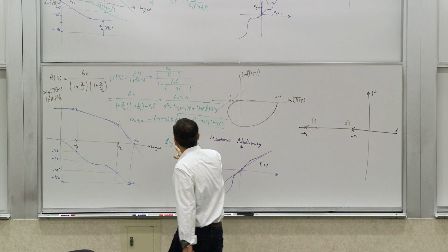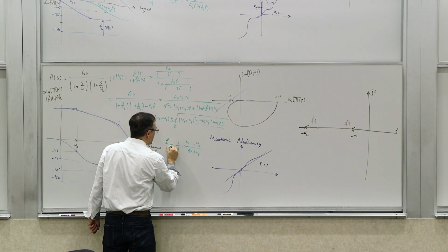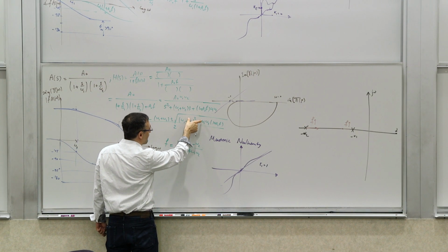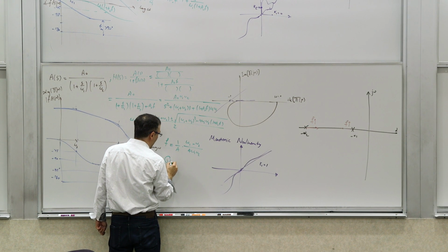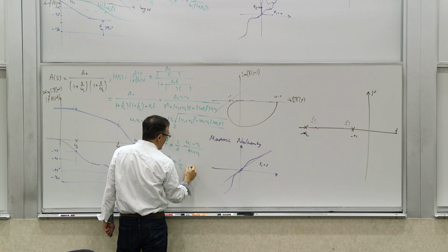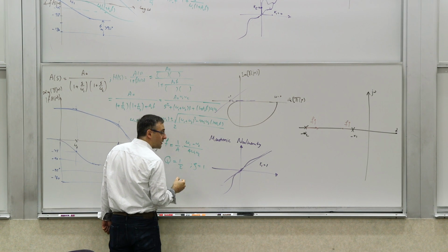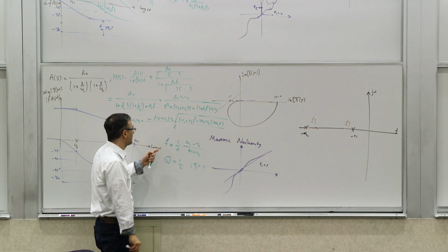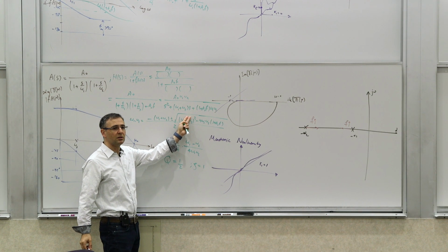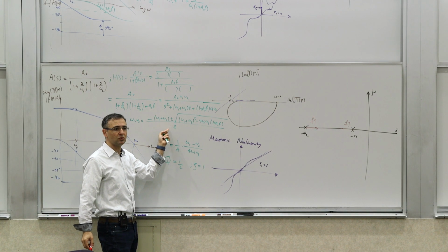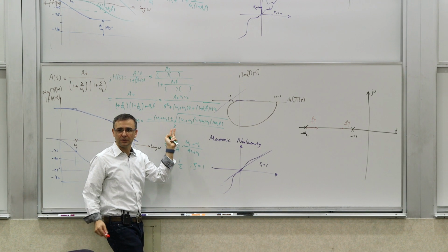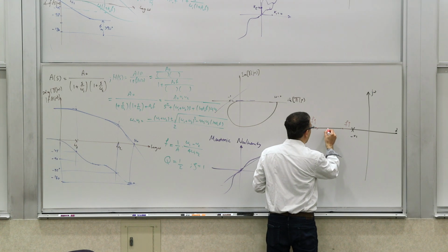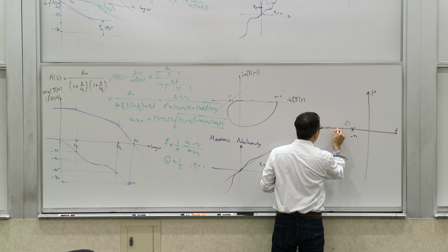At this point you have overlapping poles, a Q of 1/2, a zeta of 1, a damping factor of 1. This is where they're colliding. And where do they hit each other? If this becomes 0, it's just the average of the two, exactly halfway in between. They meet exactly halfway and would be on top of each other.